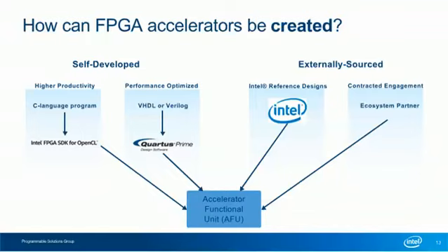If you're looking for a software-centric way to develop FPGA IP, the acceleration stack supports an OpenCL flow through the Intel FPGA SDK for OpenCL. In this scenario, Intel provides the OpenCL board support package, and all the user needs to do is to develop and optimize their OpenCL kernels for the FPGA in the C-based environment. This approach makes FPGA development easy and accessible to parallel software developers.